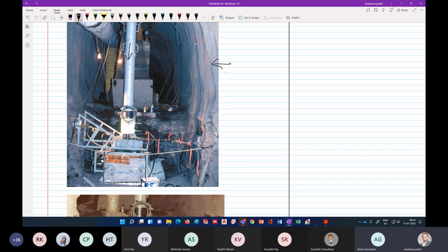We don't disturb the sample because when you cut it and take it to the laboratory, maybe the joint surface gets damaged. So you just carefully cut the sample and then we apply this vertical load. So this is for sigma n, and then we apply some shear load to test the specimen, to get the properties. So this is called in situ shear testing. Is this clear?